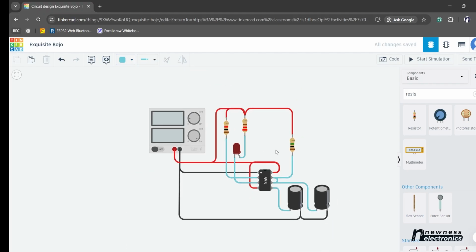This is so that the device should not trigger until you trigger it, right? If you want to trigger it automatically, I will show you another way to do that without leaving this pin floating. If you leave it floating, it means that anything can trigger it. Anything can happen that will just trigger your circuit, and that's not what you want, right?